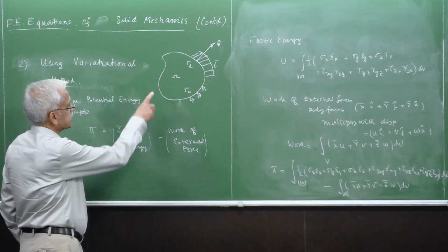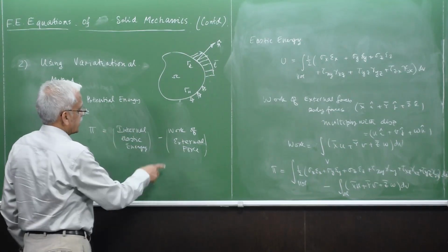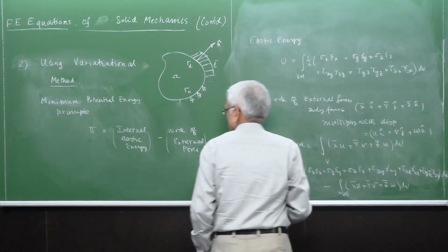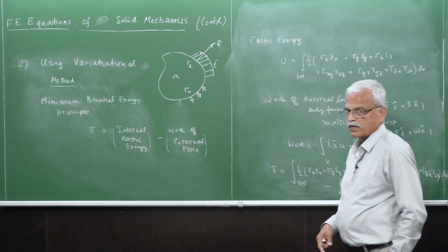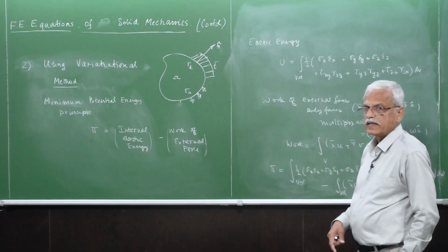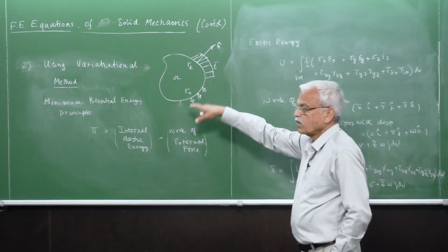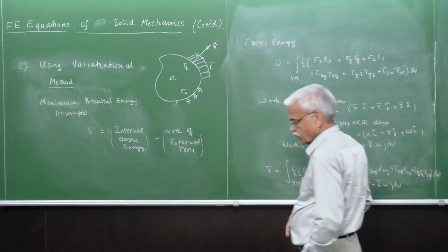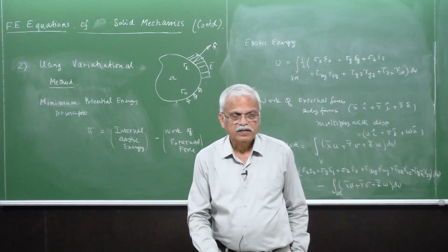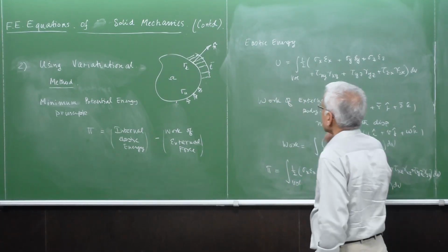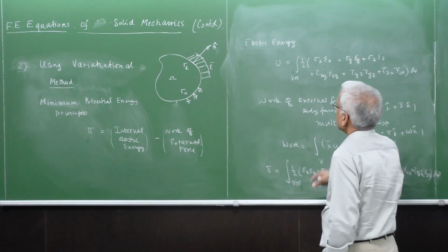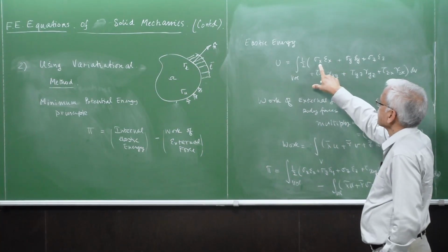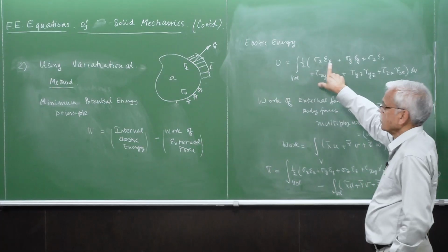Internal energy is due to the elastic energy, elastic deformations, and then the work of external forces with a negative sign here. So this is, as I remind you, linear elastic solid mechanics, and this is applied to linear solid mechanics. So the nonlinearity can be taken care of in some other way later. In this, we formulate the elastic energy to start with. Elastic energy is the multiplication of the stress and strain. So this is how it is defined.